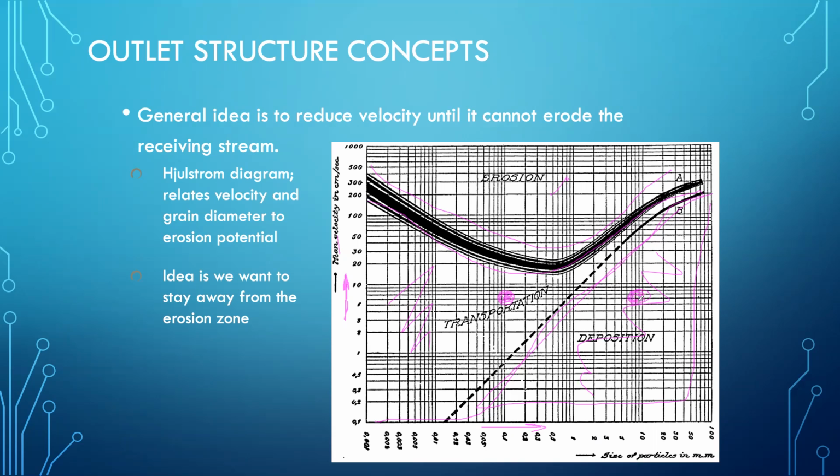If we plot over here, the chart is indicating to us that in that system, the solids are likely to deposit somewhere in our channel, and the water moves on downstream as clear water. If we stay at the same particle size and increase velocity, it plots up in this region. The chart is conveying to us that in that system, whatever the natural channel is made out of is going to tend to erode away.